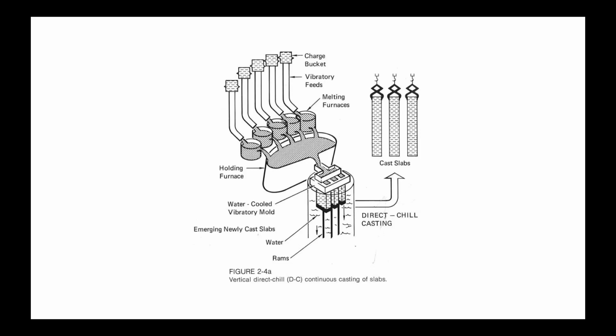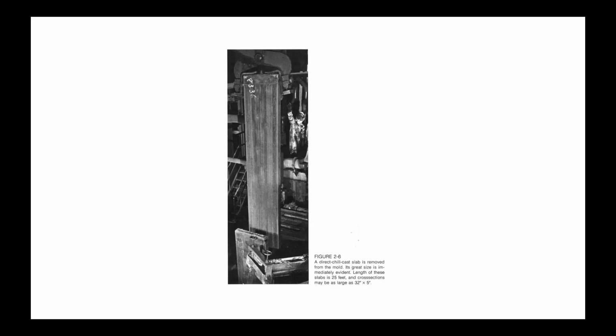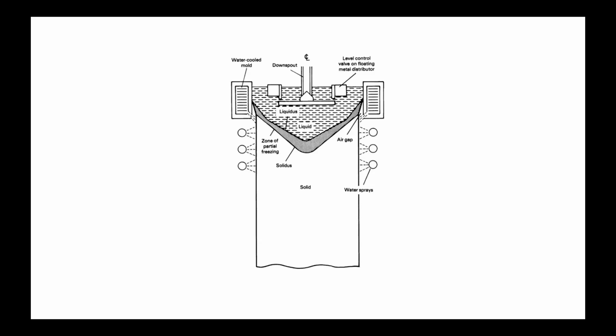Anyway, this is semi-continuous casting because you have to stop at some point. The platform at the bottom of the pit ends up reaching its full travel. You have to take the slabs out, remove them, but in the process of doing this, you have a liquid metal, solid metal front. And in close-up, this is what it looks like. The gray or dotted gray area is semi-solid metal. What it says as solidus is when it fully solidifies. The word liquidus is at the liquid to solid interface.